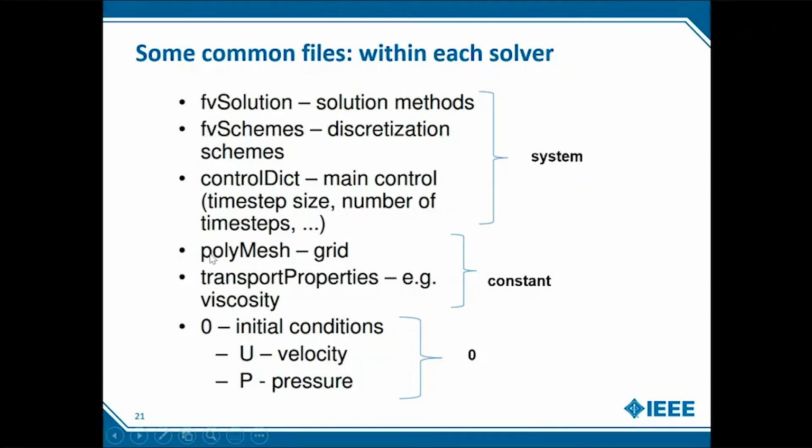So this is not of use to the user. It's mainly this transport properties file in which you define all your constants. And finally, the system folder. So system folder has 3 different subfolders. So this system folder is where your CFD modeling comes into picture.